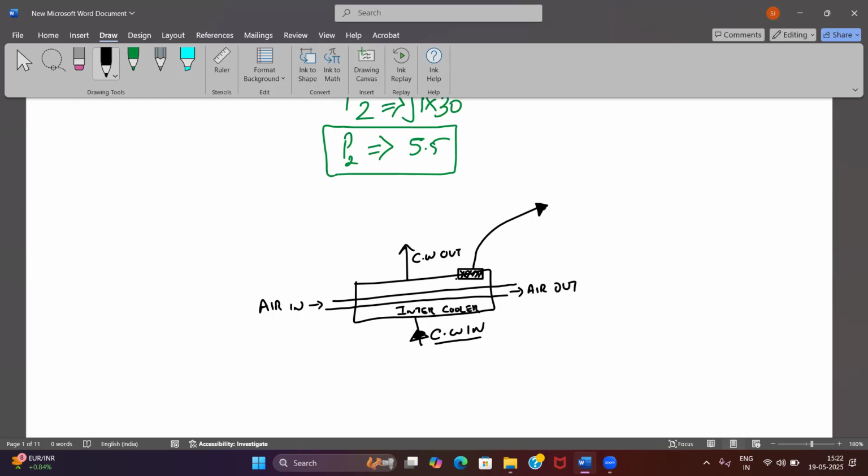So at least with water pressure, it should not burst. Water pressure is generally not more than 3 bar. But the disk should also not burst above the first stage pressure, which is around 6 bar.